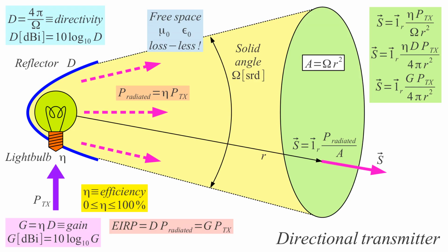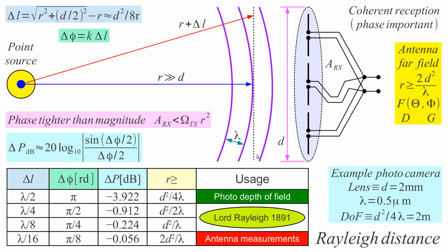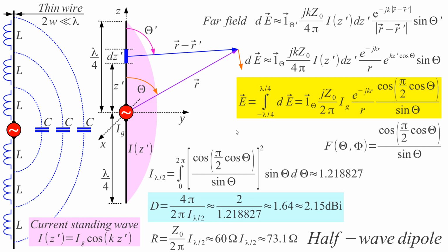So now we have to look whether we are able to do anything better to fit our equations. These equations are valid, but now the engineer has to build an antenna with useful gain, some useful efficiency, some useful directivity. That's what the engineer has to do. What we can do is actually use a longer wire, a longer wire that's perhaps 1/2 of the wavelength long. In fact, Heinrich Hertz already used such a transmitter.